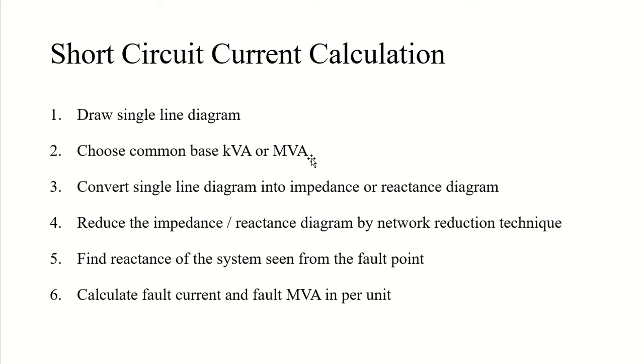We will be neglecting almost every other detail except for reactances. So let's see. The first assumption is that as compared to fault current, load current is very negligible, so we will neglect the load current. Then the shunt capacitance of your transmission line will also be neglected, which we do in most of the numericals, if you have seen the numericals in previous lectures as well. Third, the shunt element in the transformer model will also be neglected, right? Because what do we do with transformers? We represent them in reactance form, right?